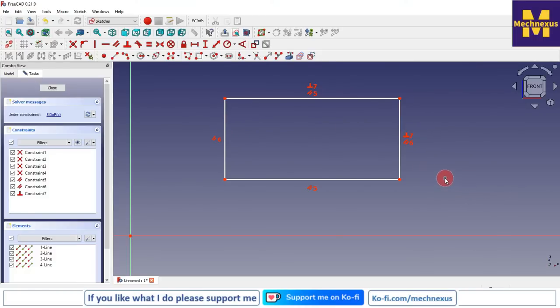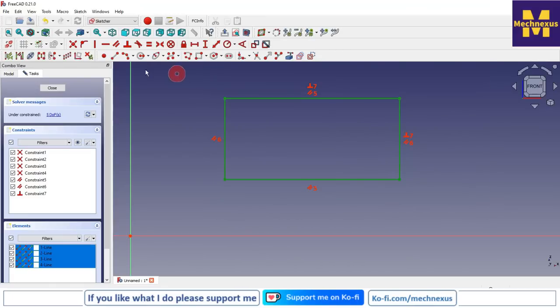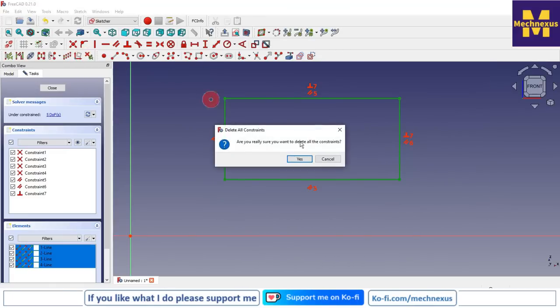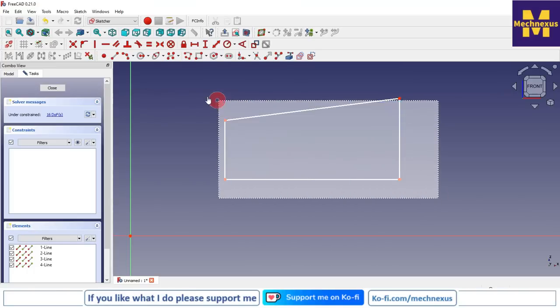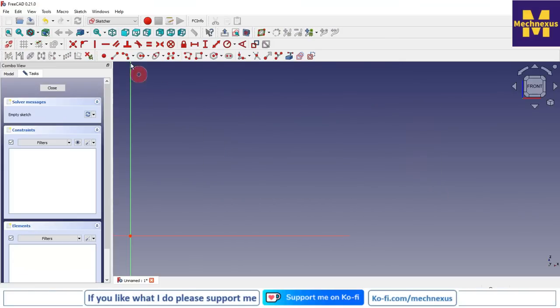Now let's move to the next tool, which is delete all constraint. So if I select my rectangle and click on it, it will ask you, are you sure you want to delete all constraints? Say yes. So the constraint got removed. Now you can give your own constraint. So this is how we have understood the essential sketcher tools in FreeCAD.